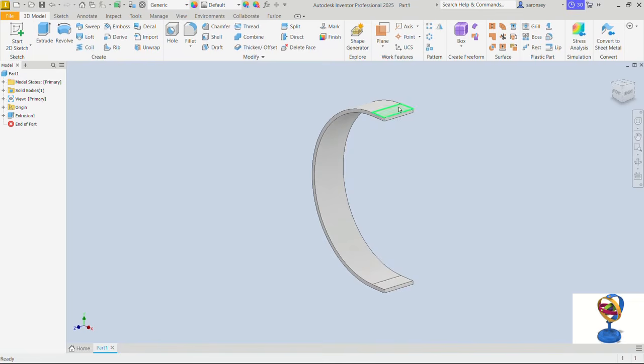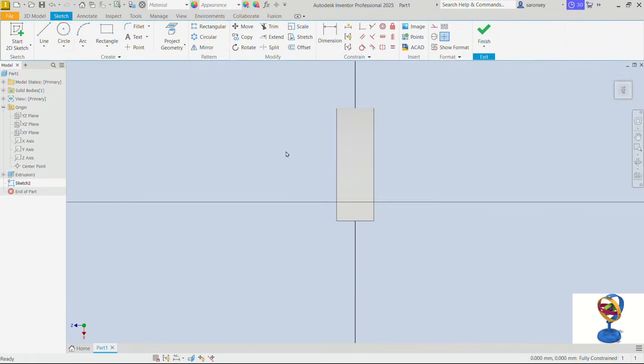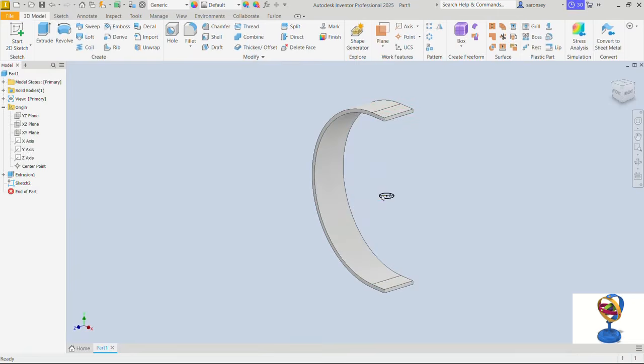Next, let's create some mounting holes. And so we'll select the plane, which is going to be the XZ plane. And let's create a sketch on that by selecting this command. Now let's pick the circle command. We'll draw a circle with this very point here as the center point. The diameter of the circle is 8. Let's enter that. You can right click OK, but we realize that we don't see the circle because it's hiding inside this feature we see here. Let's choose slice graphics so we see the circle. That is fine. Let's finish this and extrude cut this profile.